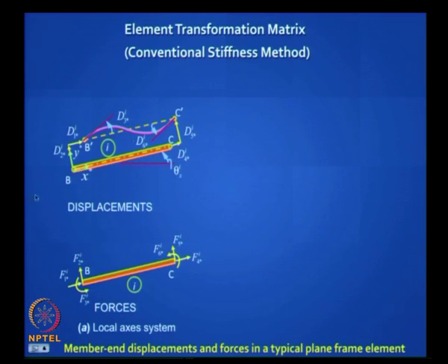Do you understand this now? If I have a force acting this way, I call it Fi2 star. Along the longitudinal x star axis, I call it Fi1 star. A moment acting this way, I call Fi3 star. These three are conjugate with these three. Can you see that? The directions are the same. One is a set of forces, the other is a set of displacements.